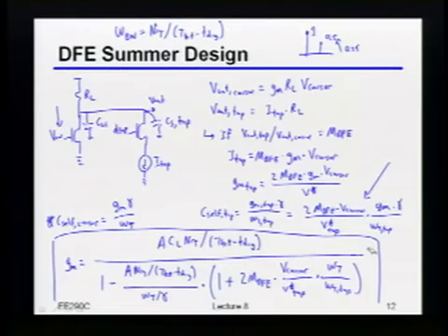Okay, that's a great question. It turns out that for exactly the reason you're asking about, and some things that we'll talk about a little bit more, even though I've said that this thing is hard switched, you tend to actually want to keep it in SAT. Because indeed, you're right, you'll pick up all of the parasitic cap from that tail current source right there.